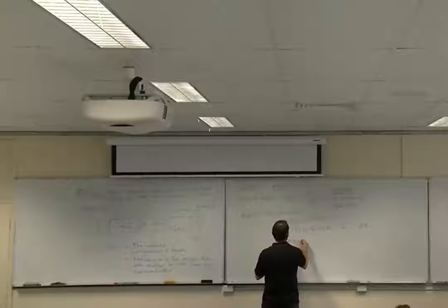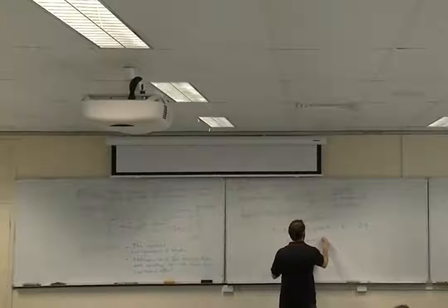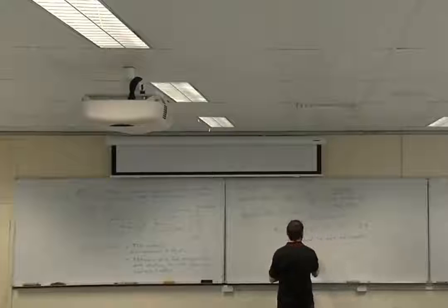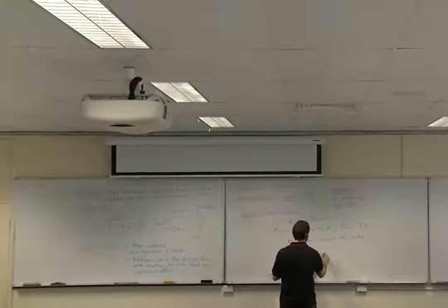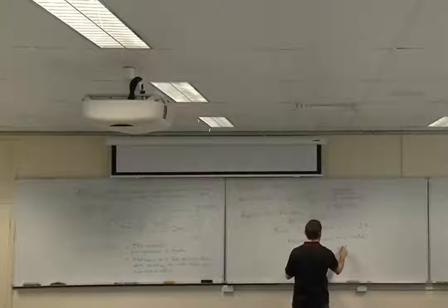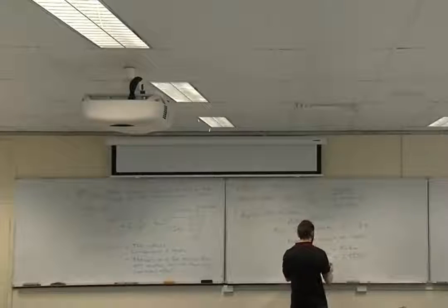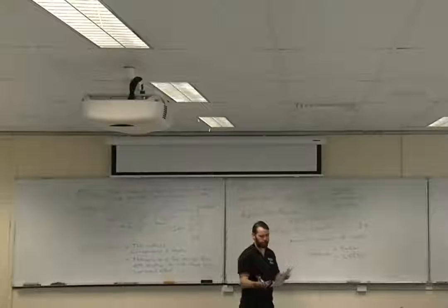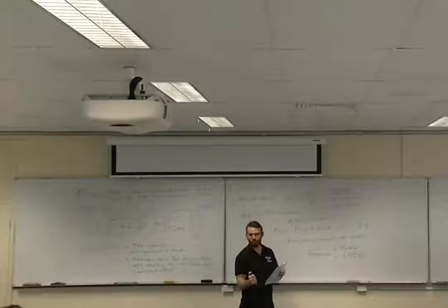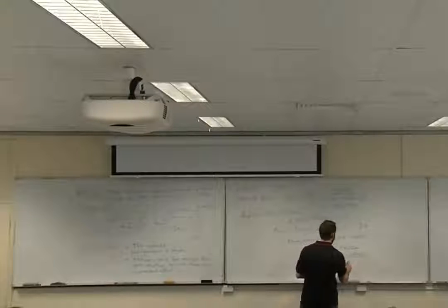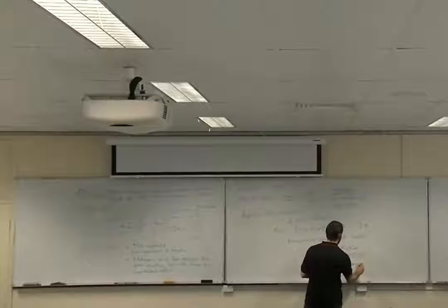Therefore, maximum stress at hole, sigma max (hole), equals KT sigma nom equals 2.5 times 36, because I'm just working in megapascals, equals 90 megapascals.